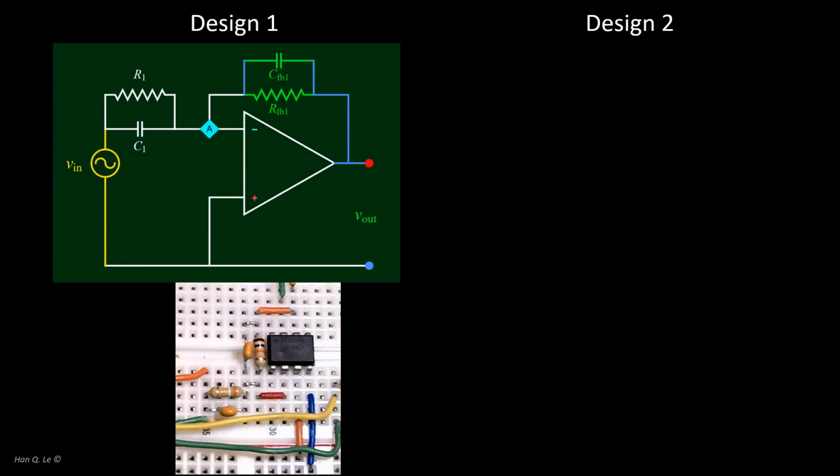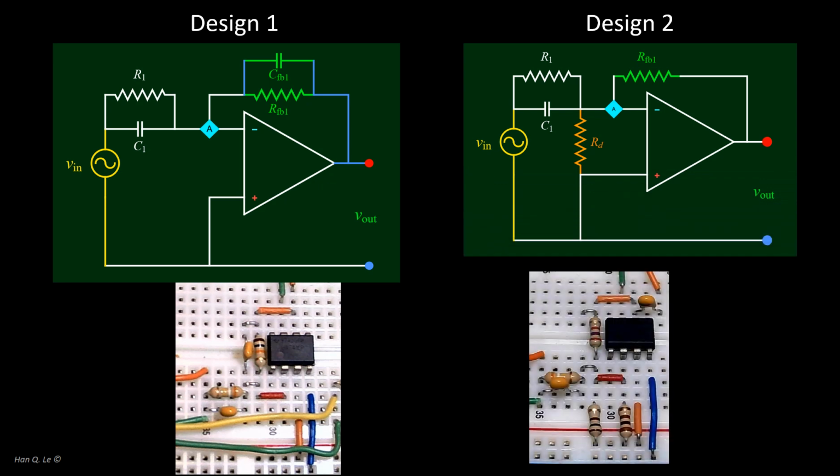There are two designs for the differentiation circuit of Part B. Check components you have and think carefully before committing to one, although it is quite trivial to change from one to the other if you have all the necessary components. Essential to design one is the damping capacitance that should be 2.2 nanofarad.